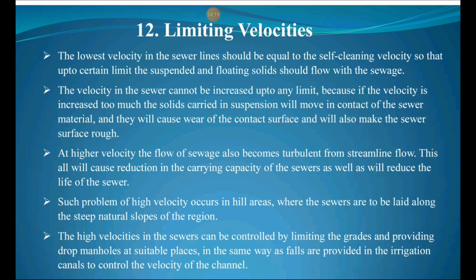That is very important, and such a problem of high velocity occurs in the hilly areas where the sewers are to be laid at the steep natural slopes of the region. The high velocities in the sewers can be controlled by limiting the grades and providing drop manholes. So one must remember, to reduce the steep grade, one must provide the drop manholes at suitable place, in the same way as falls are provided in the irrigation canals to control the velocity of canal or a channel.